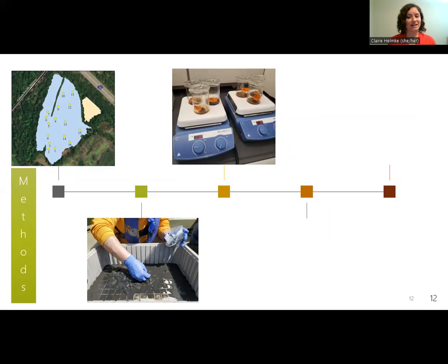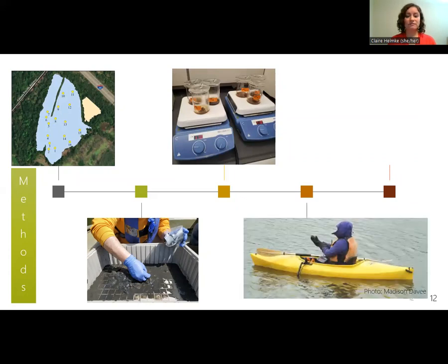So we need to figure out how to collect depth from our sample locations. Using a Lowrance Elite 5 fish finder and sonar with a transducer mat attached to a kayak, we collected bathymetry data in November of 2021.